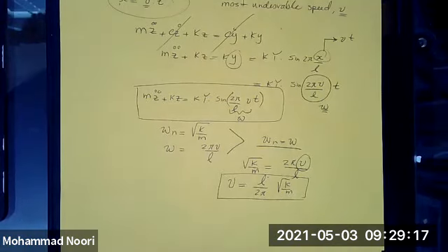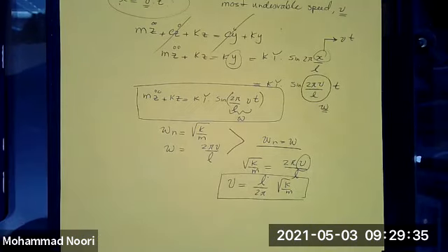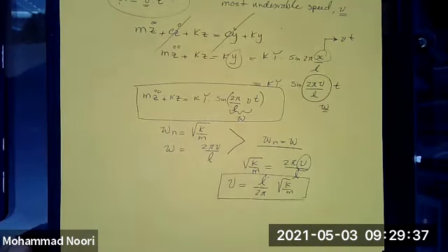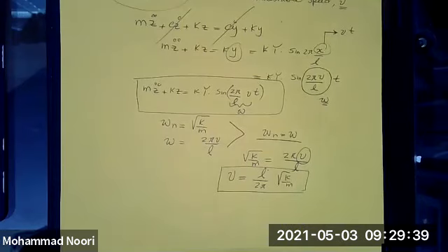So now that you have learned this, you can go to your friends who have not taken the course in vibration and you tell them, you know what? Let's assume that the road roughness on California Avenue is sinusoidal. So I'm going to advise you what speed you should avoid when you're driving on that road so you don't feel dizzy.